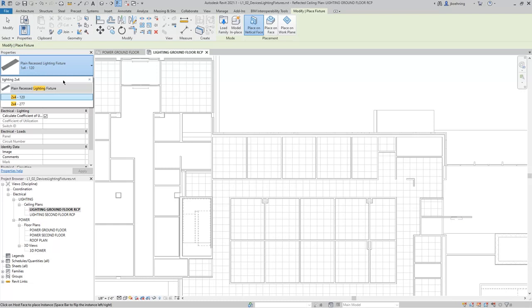Now it is important that the spacing matches though, and let me show you what I mean by that. If I type 2x4 dash, then everything goes away. But if I type 2x4 space dash, then the dashes will highlight. So the spacing in there matters, as well as the text strings, but they do not have to be full text strings. It will also work off of partial text strings. So if I type light 2x4, those partial text strings will highlight. So the search field is a quick way to help you narrow down a type that you're looking for.